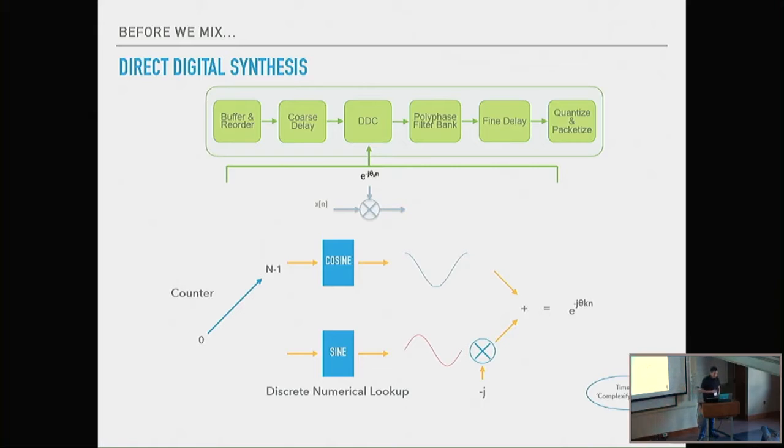What we're actually doing in the MeerKAT case, we need all of our F engines to work in lockstep. Well, we need to work on the same timestamps, so we use the lower 28 bits of our timestamp coming in. Jason did talk about timestamps in his talk briefly. That is part of our lookup, so we know that we're looking up exactly the same values for each board at the respective point in time. That is then put into our mixer, and we mix with our input data.